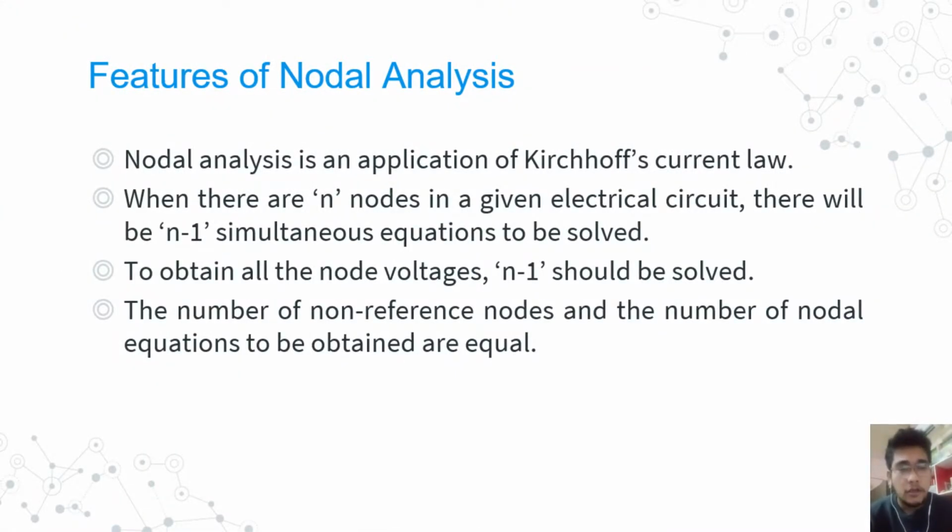Features of nodal analysis. Nodal analysis is an application of Kirchhoff's current law. When there are n nodes in a given electrical circuit, there will be n-1 simultaneous equations to be solved. To obtain all the node voltages, n-1 equations should be solved. The number of non-reference nodes and the number of nodal equations to be obtained are equal.